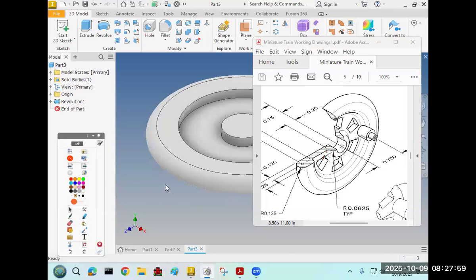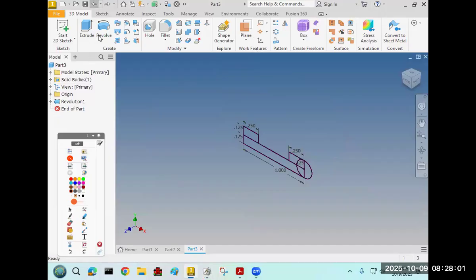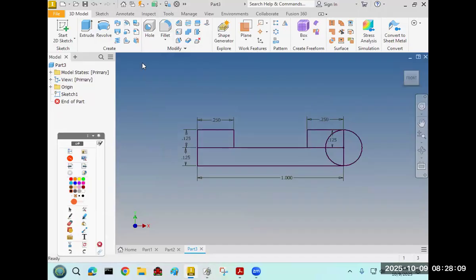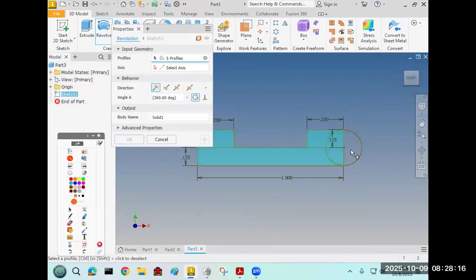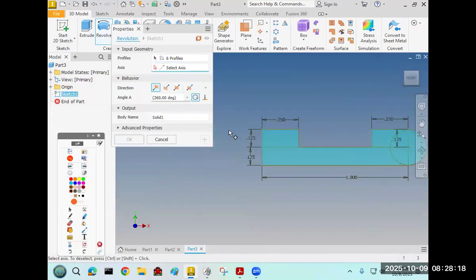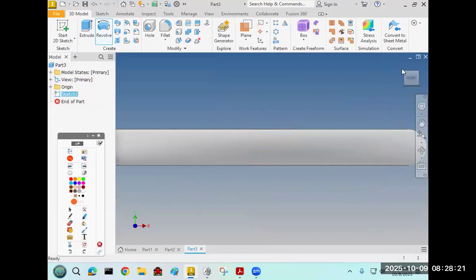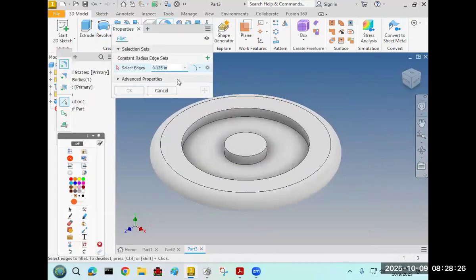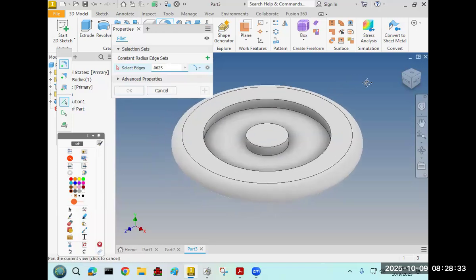I've shown you this before, how the fillet tool for sketch is kind of sketchy. Actually, you can't even do that. No, let's go revolve. We're going to do the part feature fillet. Once we have this, we're going to go fillet. We'll set the dimension to 0.0625. If you do 0.625, it's going to get mad at you.